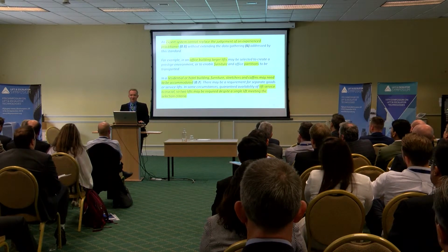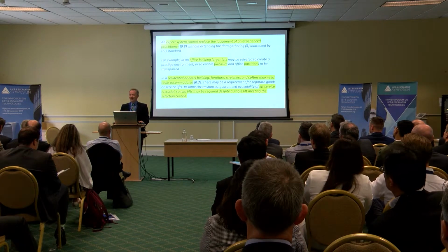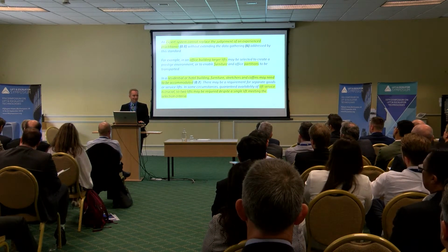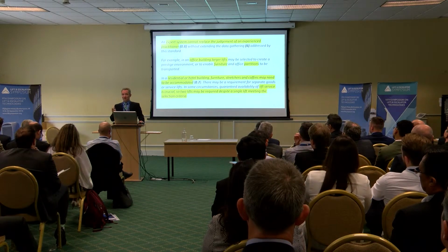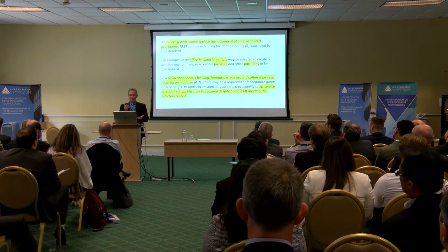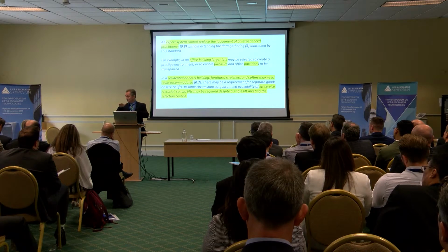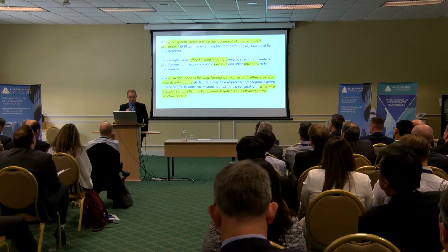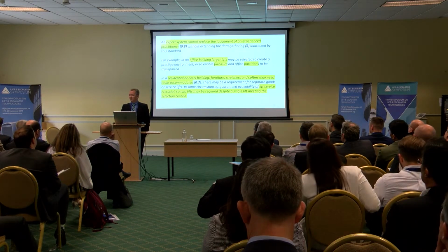You'd probably put, in a 2 or 3 story, you might put 630 kilogram office building, but in a higher one, you might have 1,000 minimum, and in an American big building you might put a minimum of 1,600. All that can be programmed. We just need the rule sets. So all that needs is, okay, if we're an office building and if it's greater than 4 stories, then we will have a minimum car size of this, and if it's more than that, so that can all be programmed. In a residential building you might have stretchers and coffins, so you need to allow for that.